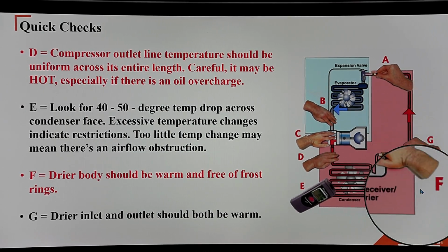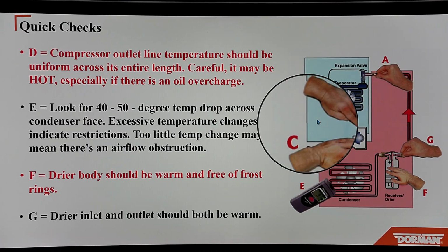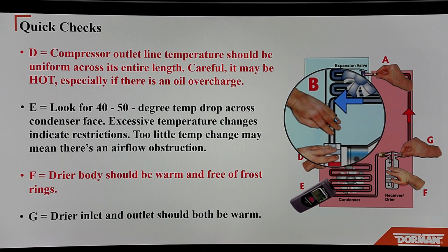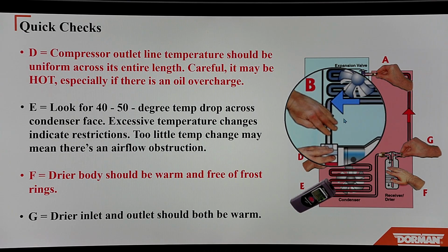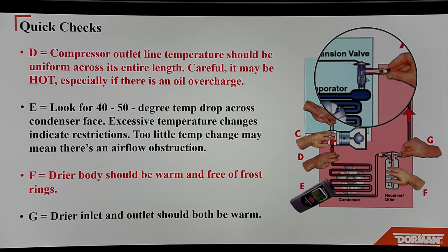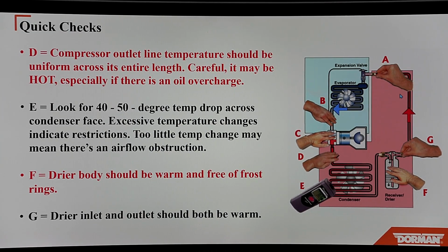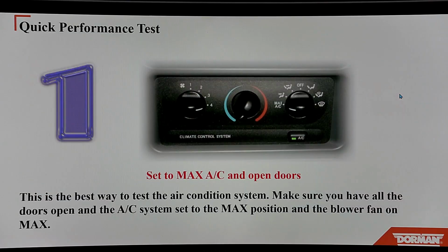And if this was an accumulator system, the accumulator would be located here. That can should be cool to the touch. You wouldn't have an expansion valve. You would have an orifice tube, which should be warm going to cold.